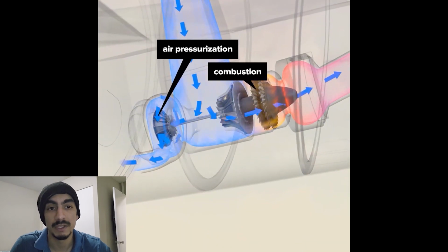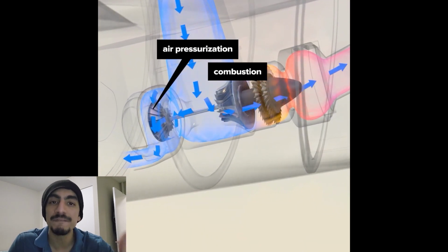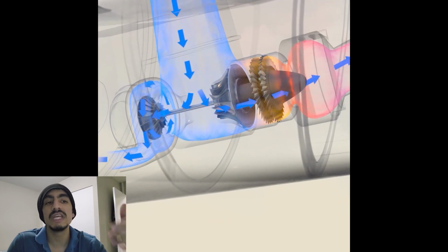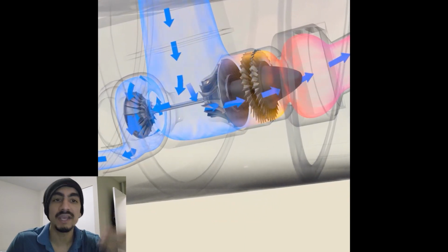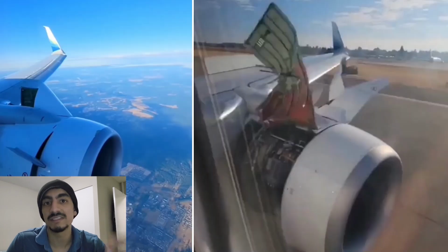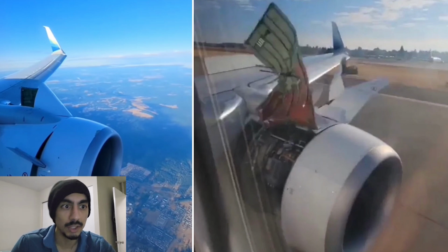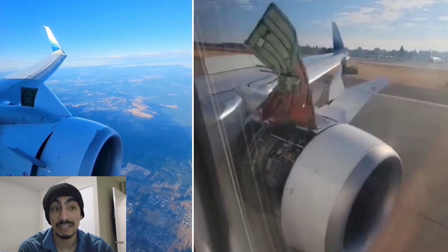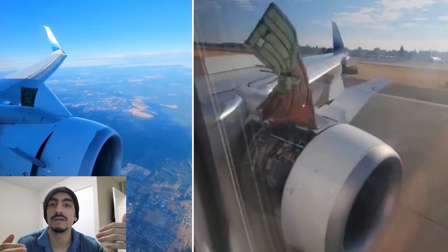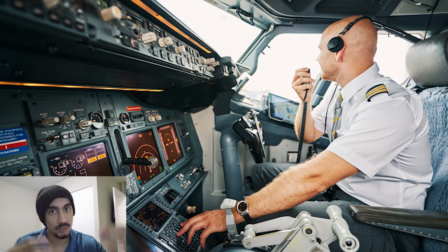So to put it simply, there are multiple layers of safety approaches that are designed, okay, to keep an airplane able to maintain basic functionality and safety in the event that something goes wrong. For example, in this instance, a bird strike, okay? Losing one engine in theory shouldn't doom the aircraft to failure, okay? You can still deploy the landing gear, you can still manage your flaps to slow down properly for landing, you can still power critical flight controls. And of course, all of that hinges on the fact that the flight crew knows the proper procedures, they can stay calm, and they can execute the right actions in the cockpit.